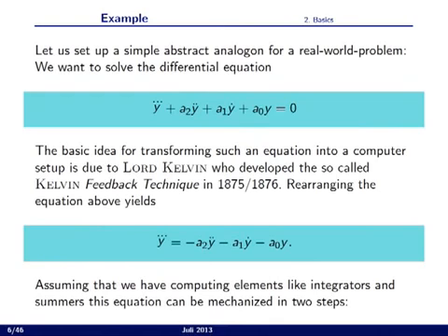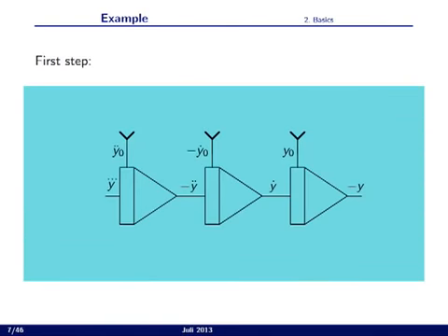How? By integration. And integration is astonishingly simple in an analog computer. You have computing elements that implement integration. Most of you will remember integration as some kind of hard operation from mathematics from school. That's not true. Integration can be very, very simple. Collect water in a bucket. That's integration. Collect current in a capacitor. That is integration. Count bits in an accumulator. That's integration. So it's simple to build an integrator.